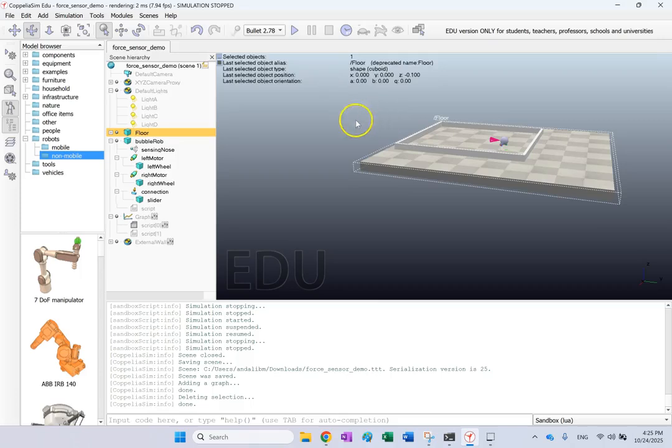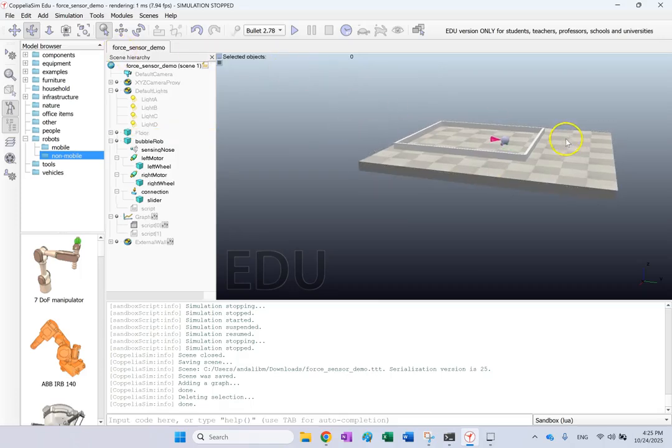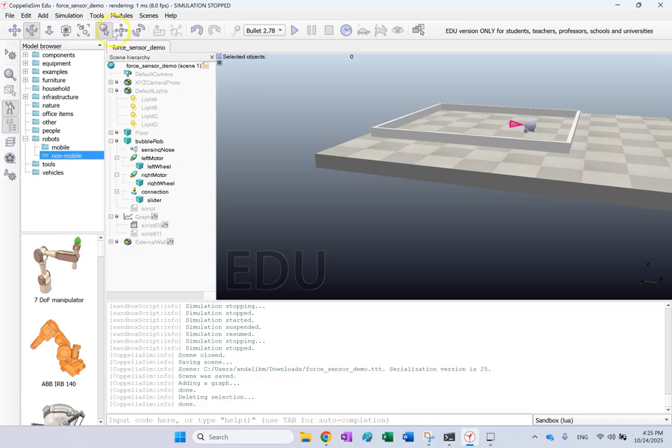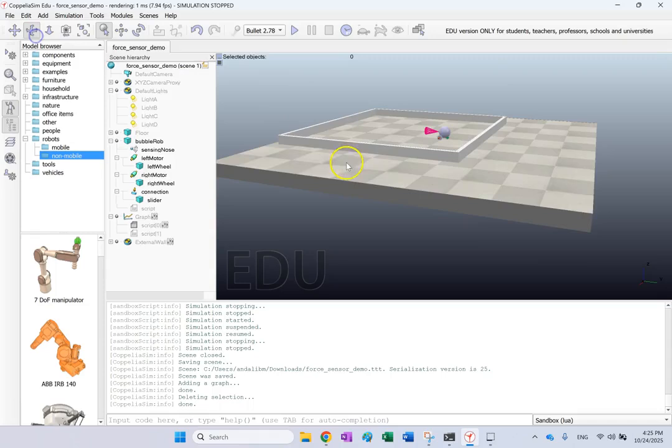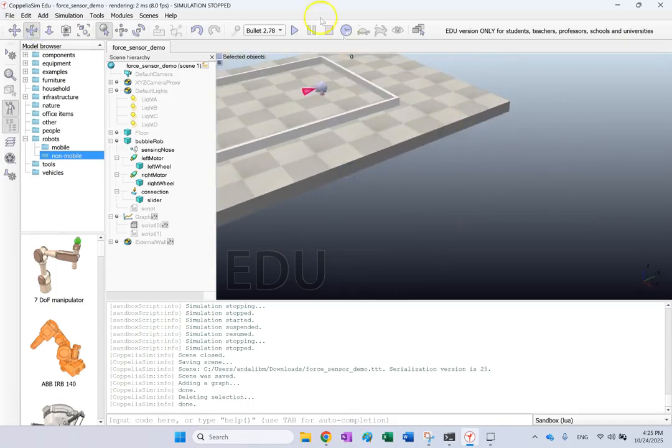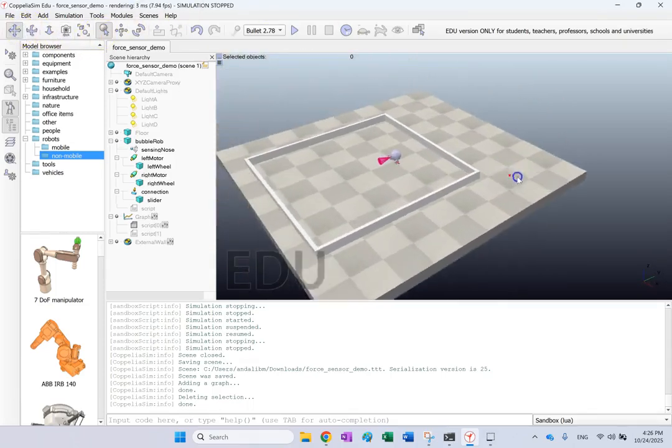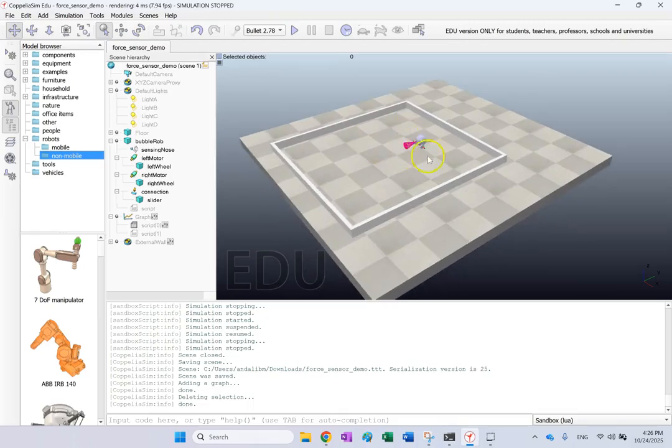So basically, that's what I wanted to say. Each object has some visibility, and it has a bit according to the way that the software allocated to them. So you saw that bit 3 was a sensor, bit 1 was a model, and so on and so forth. And the other properties of these parts, including detectable, measurable, respondable, all of those, they also have some kind of bits too. They are all 16 bits. But here, what I wanted to show you was specifically the visibility layers, okay? So that's one thing I wanted to show you.